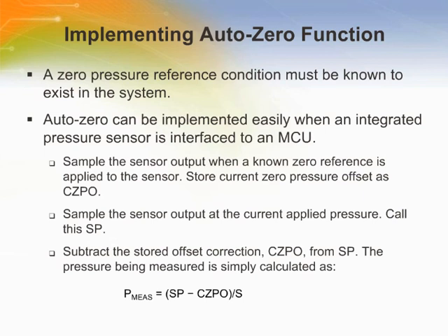Auto zero is a compensation technique based on sampling the offset of the sensor at reference pressure. Atmospheric pressure is the zero reference for a gauge measurement, in order to correct the sensor output for long-term offset drift or variation. Sources of offset errors are device-to-device offset variation, trim errors, mechanical stresses, mounting stresses, and shifts due to temperature and aging. Performing auto zero will greatly reduce these errors.